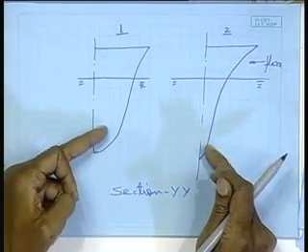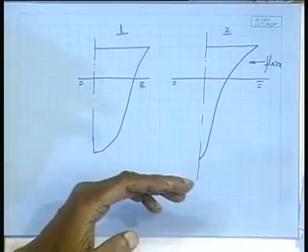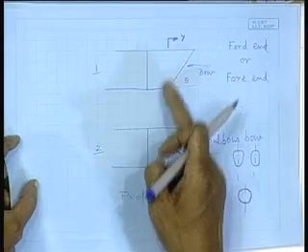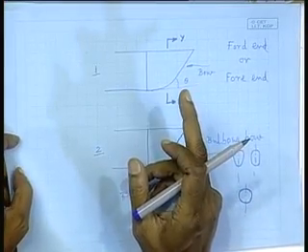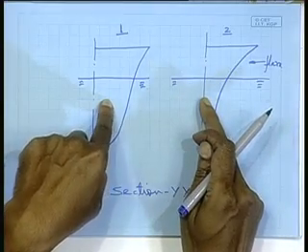Let us assume that these two sections are taken more or less at the same location of two near identical vessels, right. Only thing, in one vessel the block coefficient is of the order of say 0.8, in another vessel the block coefficient of the order of 0.6. So, 0.8 would be somewhat like this, 0.6 would be somewhat like this.